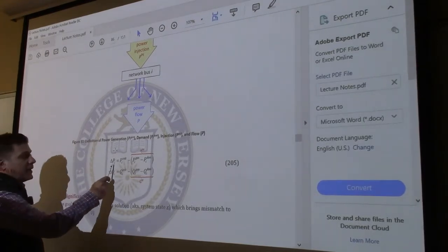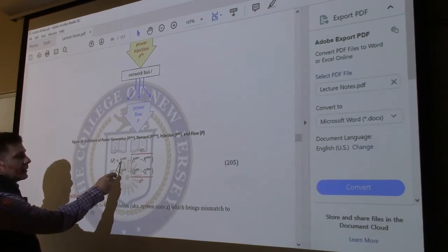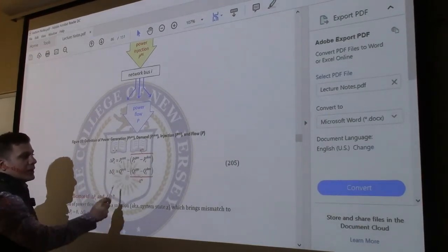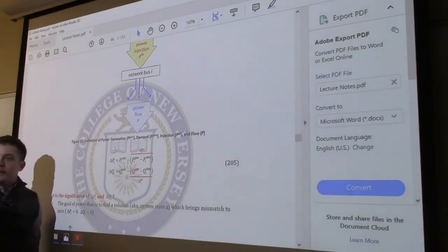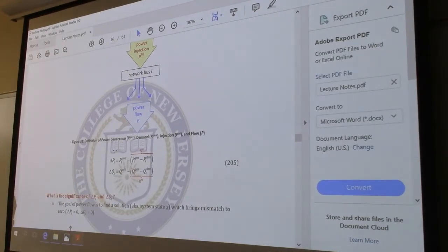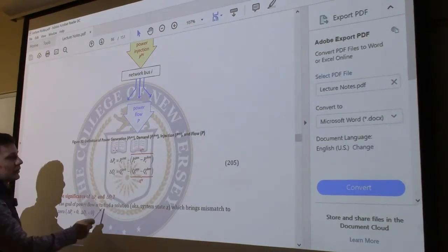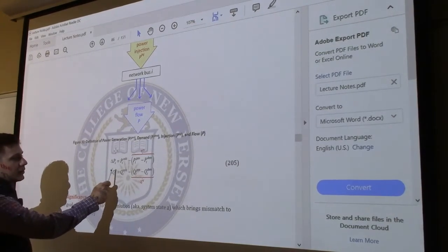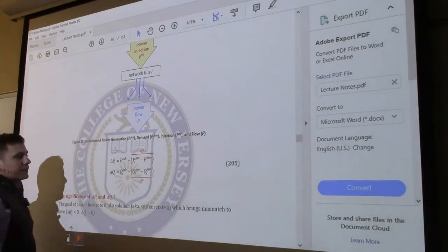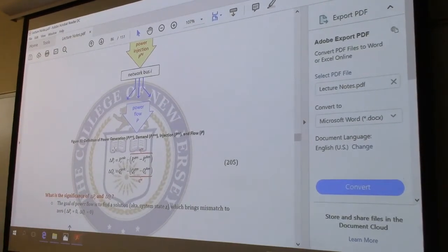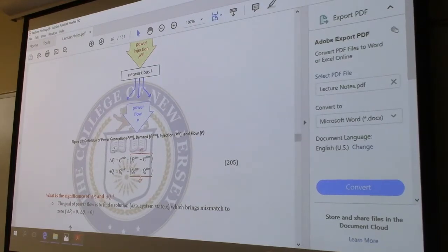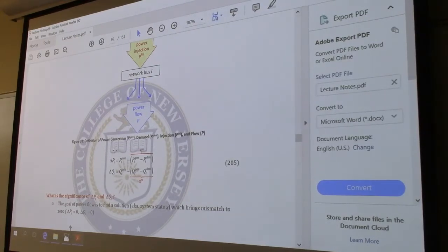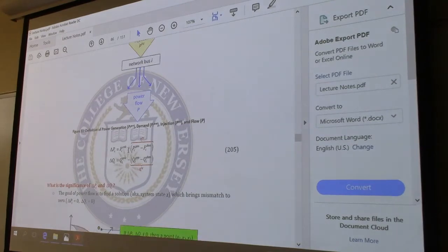The mismatch in P for bus i will be equal to the calculated value minus the injection. You can also break the injection down to the generated minus the demand, like the example that I just gave. Same thing for Q. Delta Q will be equal to the calculated Q_i minus the generation minus the demand.